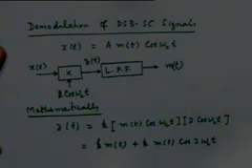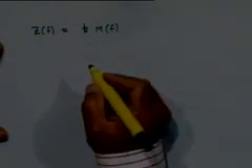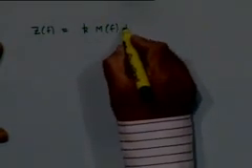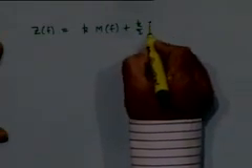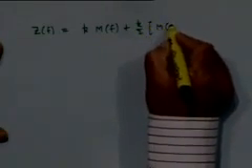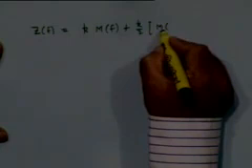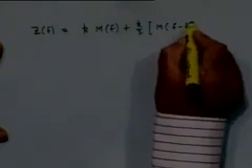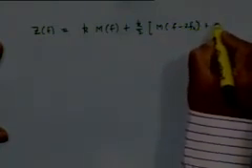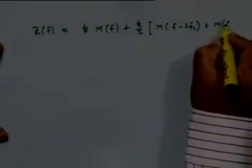And in the frequency domain, if I take the Fourier transform of this signal, the first part will have a Fourier transform which is k times the desired spectrum M of f, plus you have components at the translated version of M of f around 2fc and around minus 2fc.